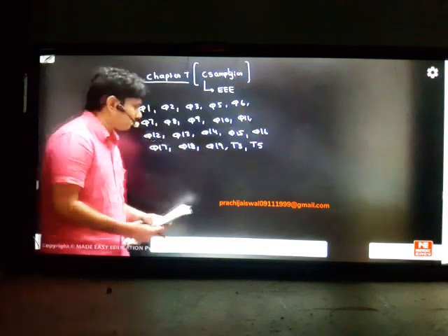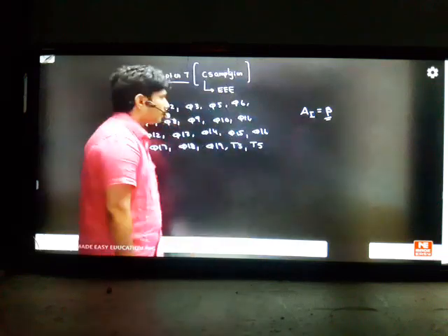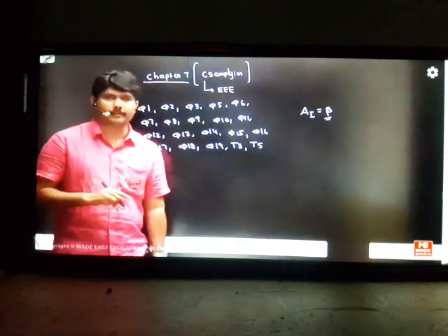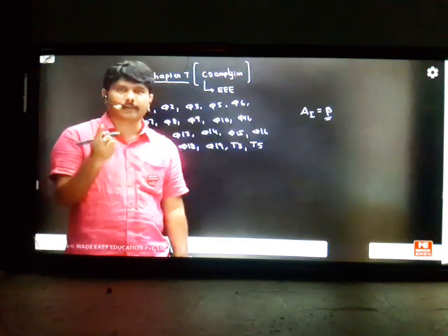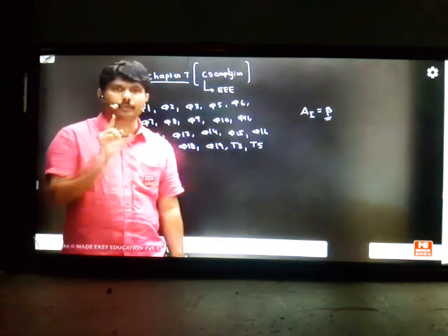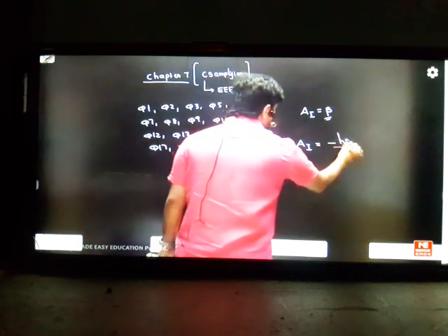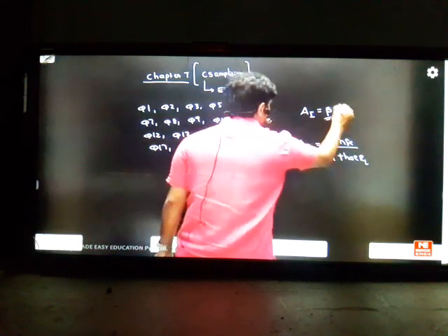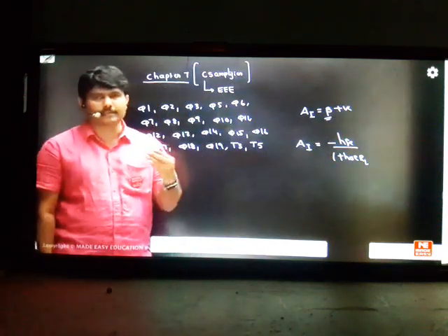Suresh Kumar, don't get confused here. Current gain is actually called beta. We never write minus beta, we write beta only. But in the problems, you have gone to two-port network theory. Because of two-port network theory, my current gain I have to take as I1 to IL. But we have taken a negative sign because I2 is coming opposite to me. That sign is not due to current gain. That sign is due to the two-port network convention. Understood? That is the reason the formula has been prepared like that, as minus HFE by 1 plus HOE into RL. But beta is positive only here. So this sign is confusing for students. That sign is not meant for current gain. That sign is due to two-port network sign.